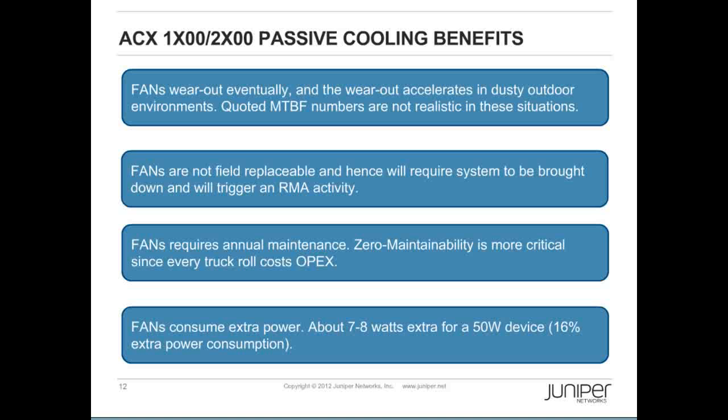Fans need annual filter cleaning, and if they're not field replaceable, a certain percentage of fans fail in a large network. Just because of the reliability curve, you need to keep replacing these units because of fan failure. And fans consume extra power. So low power, which comes as a benefit of passive cooling, also benefits from the lack of fans.